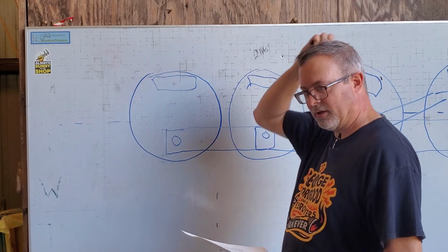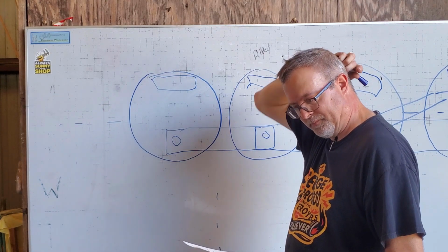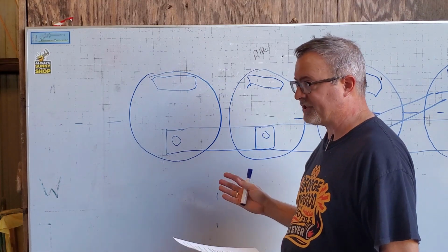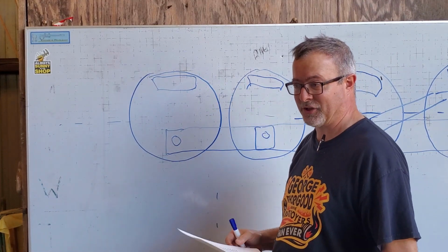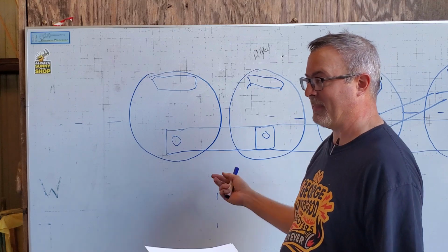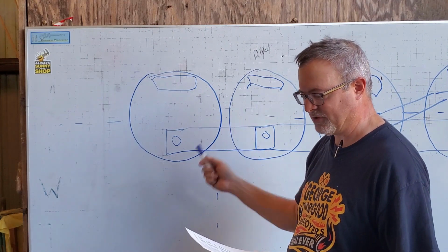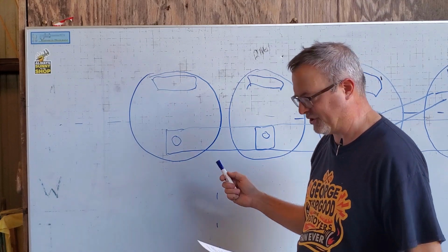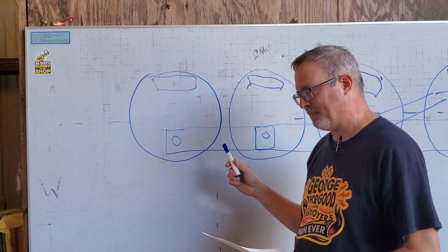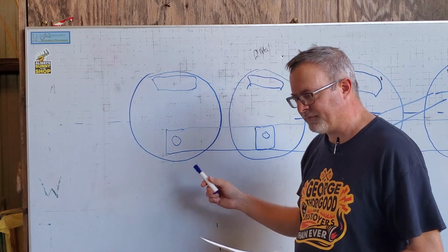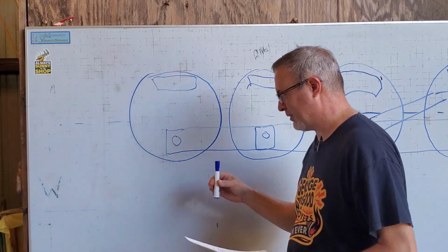As far as the flywheel affecting governor operation, I would say improve the design of the governor so that you can still run a massive flywheel and have a sensitive governor to change speed. And I've talked about the governor for the Skinner engine. It's not so much a centrifugal governor as it's an inertial governor.